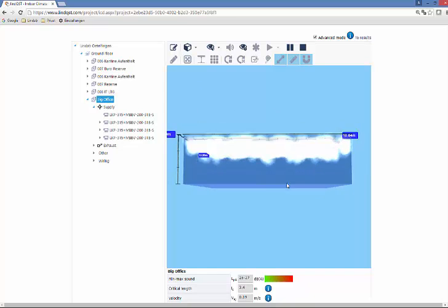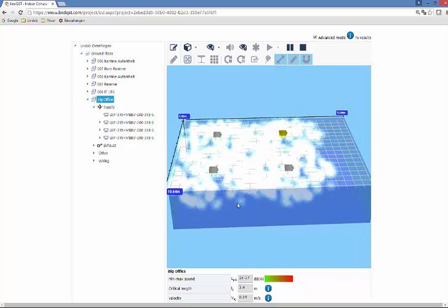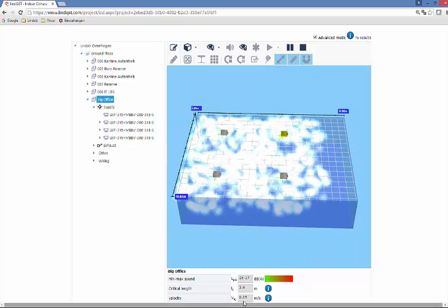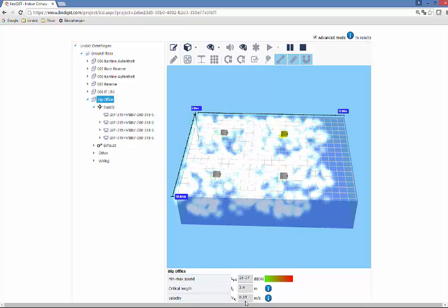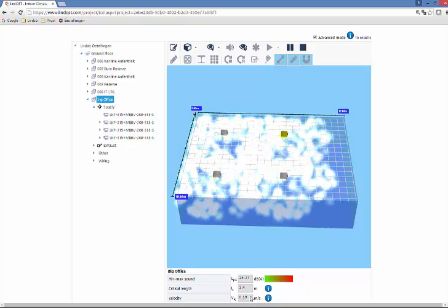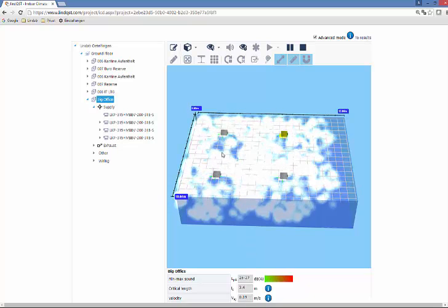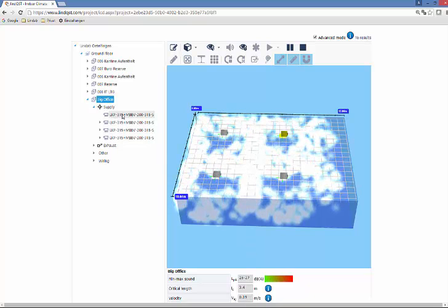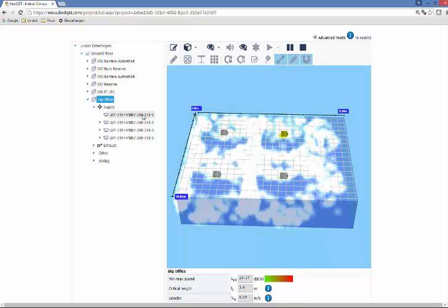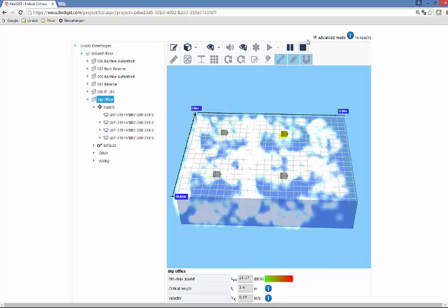And then you can see here the room is completely ventilated, which is exactly what we want, but we do not overload the room with too high velocities. It's just 0.19 meters per second. So this selection is the right one, LKP 315 plus MBBV box with a connection 200.